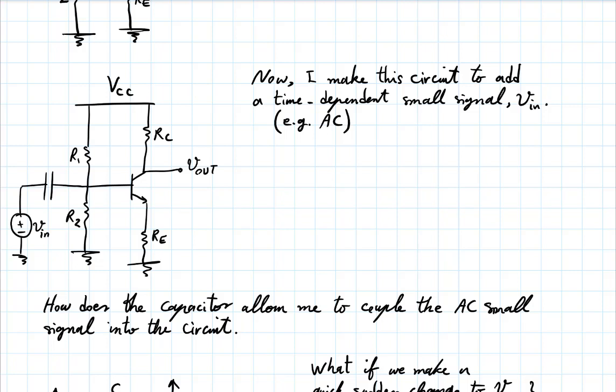Yeah. So consider this. Let's put some numbers to it, right? Assume this is 20 volts, right? And you solve this circuit. You find a bias point depending on these resistors. Your base bias could be at, let's say, 8 volts, right? Think about some example we did last week, right? Something like that. This capacitor in DC has no effect, right?